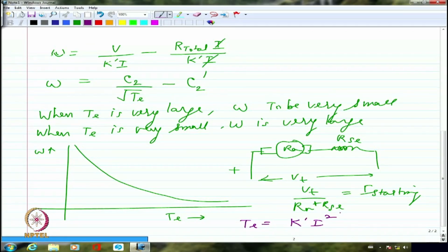This is what we said as the torque. So the torque generated is extremely large. If the current is very large, the starting torque is also going to be extremely large. So series motor is one motor drive which can really generate a very, very large starting torque, that too controllable. If I put an external resistance in series, I can control that resistance as per my whims and fancies, no problem. Correspondingly, I would be able to control the starting torque quite effectively in a series motor drive.